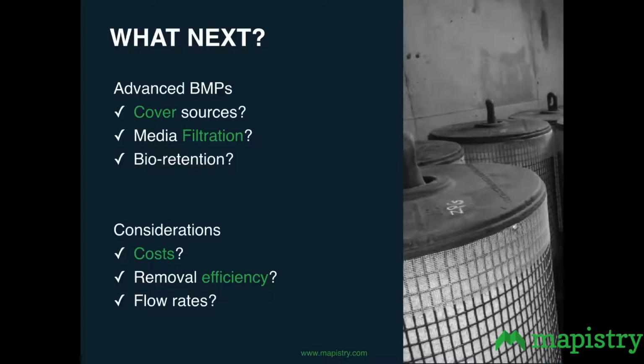If those first-line BMPs aren't working, can you cover sources? Can you temporarily cover sources prior to rain events? Can you pull tarps over them? Can you cover them up? Is some sort of media filtration, like a sand filter, necessary? Sand filters can handle really high flow rates, really robust. If you have TSS issues, it may be worth installing a sump and pumping into a sand filter, or installing a sand filter.